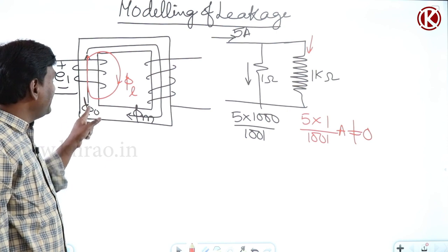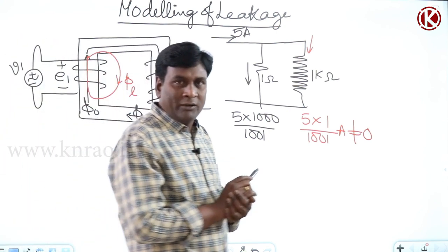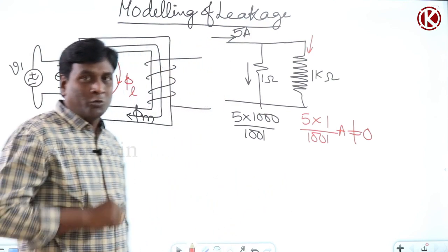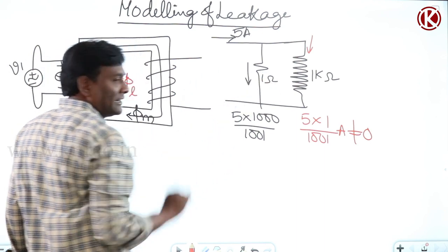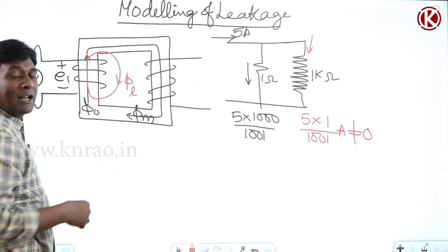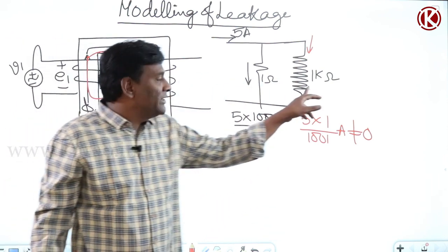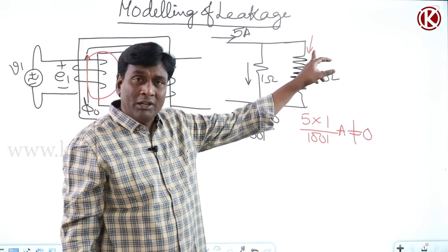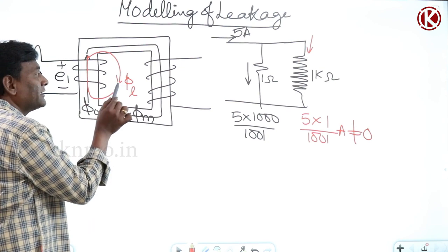Why? Basically, for phi naught, in an oversimplified way, there are at least two reluctances. What are those? A very low reluctance here, like very low resistance, and a very high reluctance here, because the flux has to go through non-magnetic material, like this. Now, though it has a very high resistance, can you stop the current? No. Though it has a very high value of reluctance, can you stop the flux?